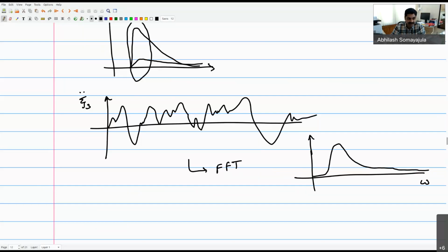Okay, so you basically see where the peak of this thing is, and that becomes your encounter frequency that you need to deal with. Now you choose your notch filter's frequency as equal to the encounter frequency so that you can filter out frequencies around this notch filter and then effectively eliminate the wave components which have significant energy. Okay? All right. Any other queries?